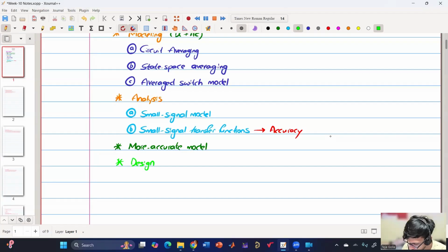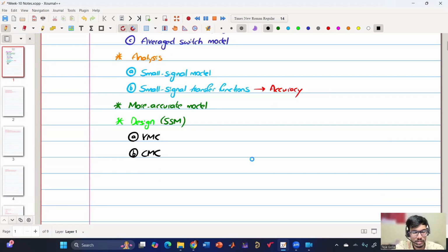So based on again small signal model, assessing small signal model. Here we have done pole zero cancellation, and then for voltage mode control as well as current mode control, and I have taught for buck, and I think Kelvin might have taken few case studies for the boost as well. And then we have seen that there is a bandwidth limitation.